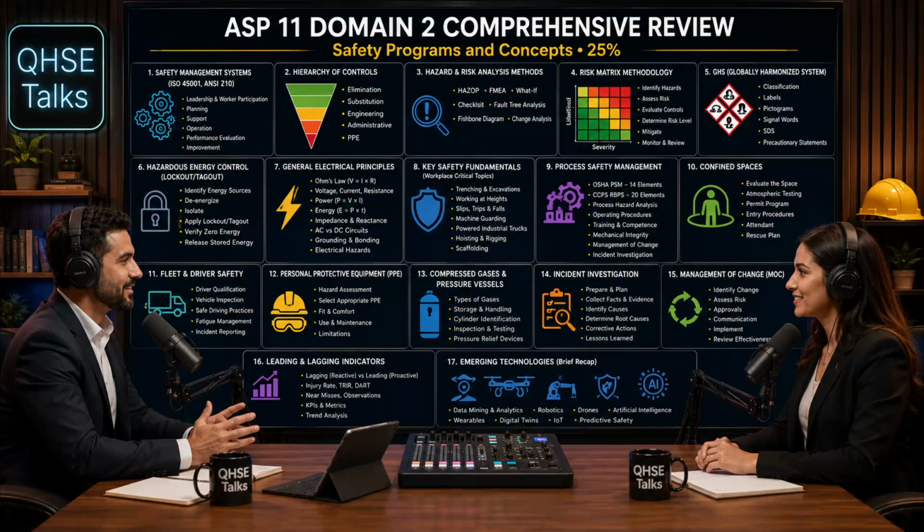So if a standard breaker doesn't protect the human heart from a lethal shock, what does? For human protection, especially in potentially wet or highly grounded environments, you must use a ground fault circuit interrupter, or GFCI. How does a GFCI know the difference between a machine running normally and a human getting shocked? A GFCI monitors the balance of electrical current moving through the circuit. It measures the current going out on the hot wire and the current returning on the neutral wire. Under normal conditions, those two numbers should be identical. Okay, so what if they aren't?